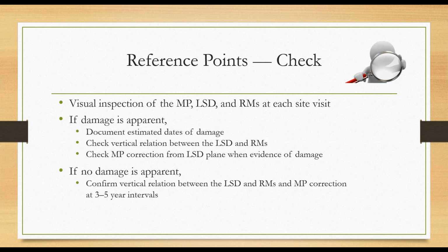If no damage is apparent, then what we require is that they confirm the vertical relationship between the land surface datum, the reference mark, and the measuring point every 3 to 5 years.